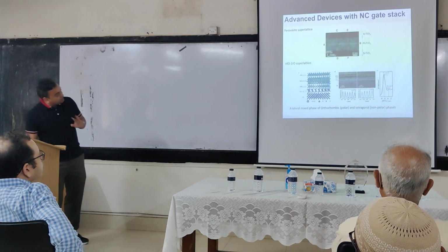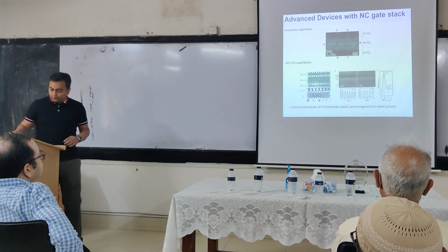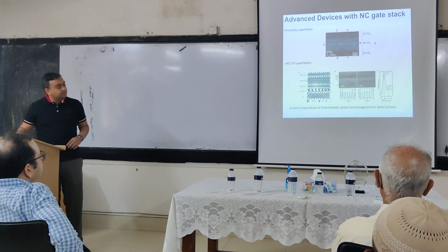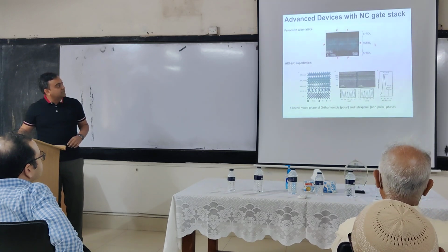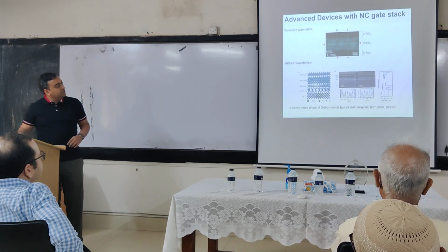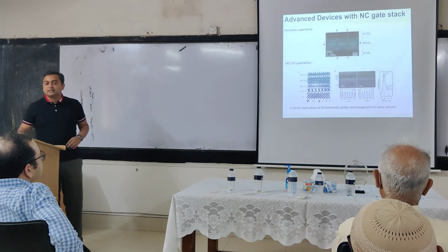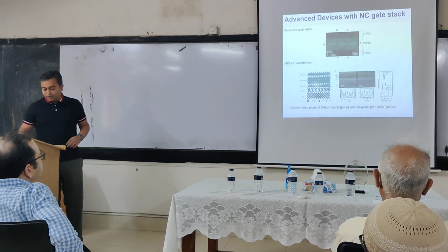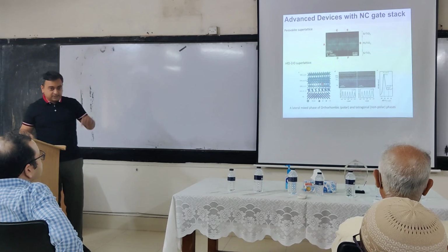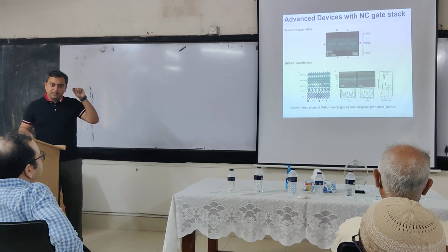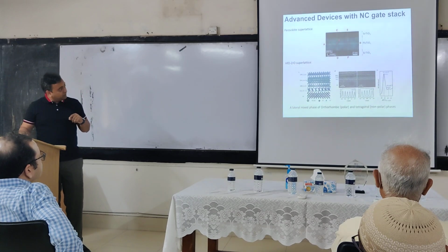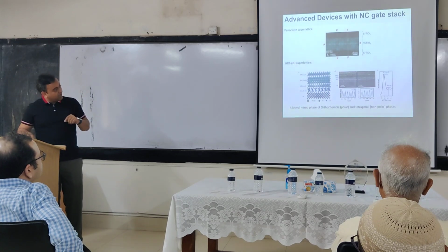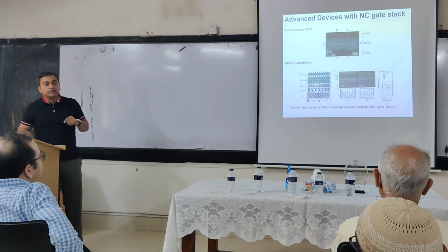But coming back to our application side, we know from our work on perovskites, this kind of material, superlattice, what we need to get very strong negative capacitance, right? And we now have this new type of material that we can stabilize at a very small thickness with ferroelectricity. So we can learn from this superlatticing, and we can try to emulate that in this very thin ferroelectric.